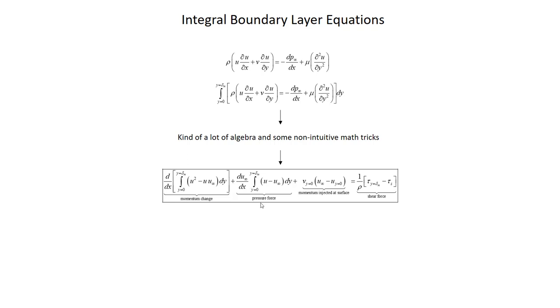And so this is actually the pressure force exerted by the free stream in a lot of cases, or at least some cases. So for example, for a flat plate, if U infinity is constant, then this term is going to be 0. But we'll keep it here because it's a lot easier to remove it than it would be to add it if we didn't have it here.